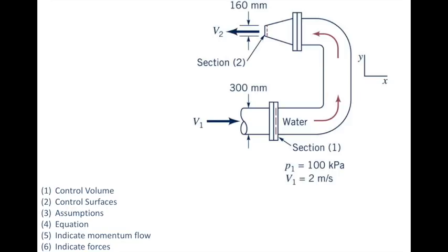Okay, so your pressures are specified with two different reference systems. Well, you need to get them into the same reference system. It's the bottom line. And it doesn't matter which one you use. You can solve these in terms of absolute pressure. You can solve these in terms of gauge pressure, but you can't solve them with a combination of those two systems. Okay, so put it into one or put it into the other. One of them is easier. I'll let you think about which one's going to be easier, and then go to it. Okay, I think you can get there.